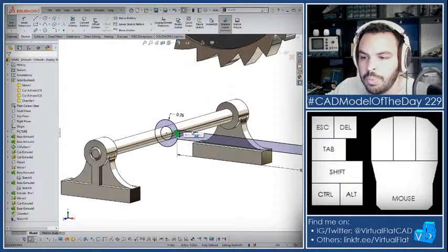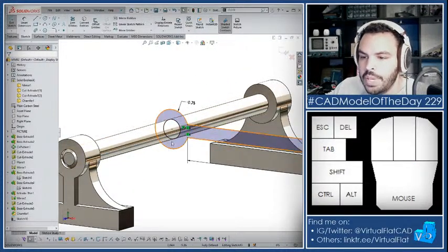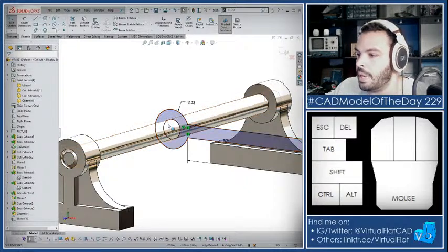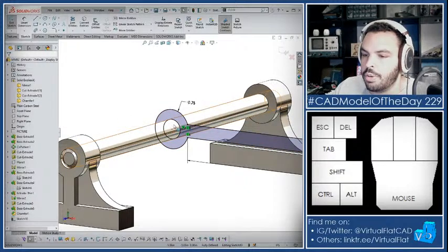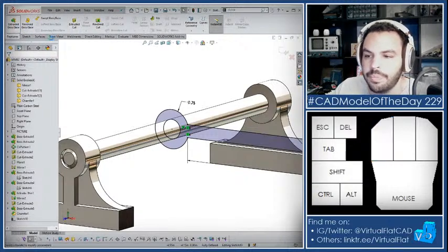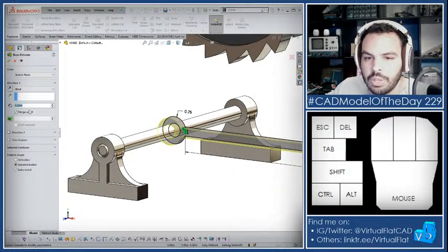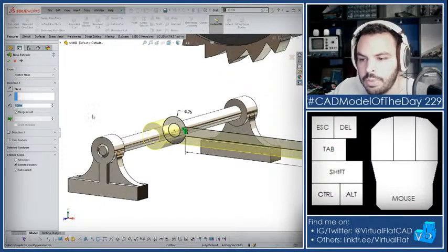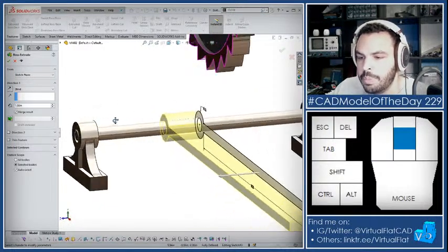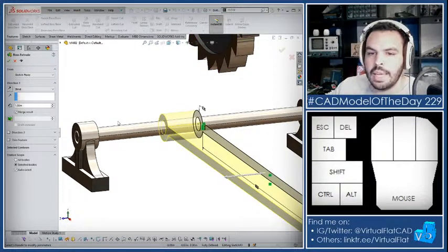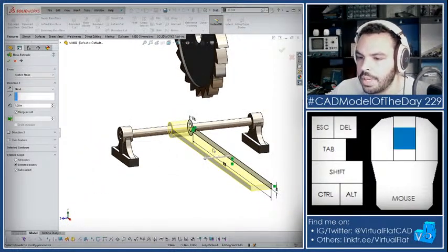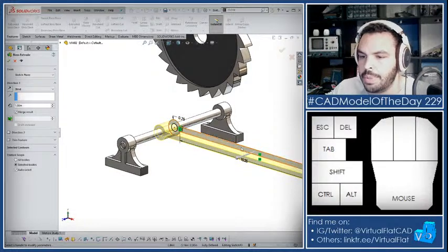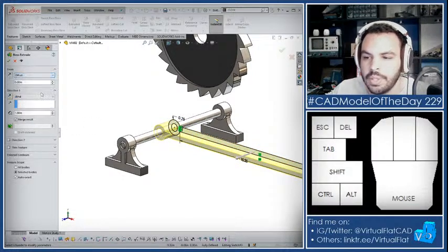All right, but I think we're ready to extrude that. The inner contour there is good because that means it won't create any material there. It'll come out with the hole already in there. So I'll extrude that, and this one's going to have to be kind of long, actually. I think it's going to have to be like 1 inch long or something like that, because again, there's going to be a connection that has to be made here.